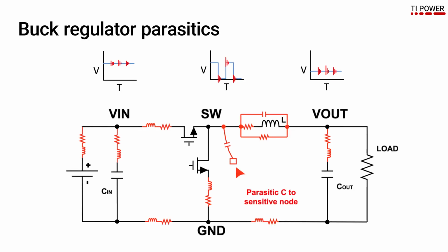There are parasitic inductances in series with the high side and low side switches, as well as a high di/dt loop area on the input side of the regulator. Most problems with switching power supplies and noise are related to these parasitic components in the design. As you can probably tell, having excessive inductance in the high di/dt loop can create unwanted ringing on the switch node, and since the inductor is not an ideal inductor, this noise can make it all the way to the output voltage. With this background of the buck regulator in mind, how can a power module help improve EMI performance?